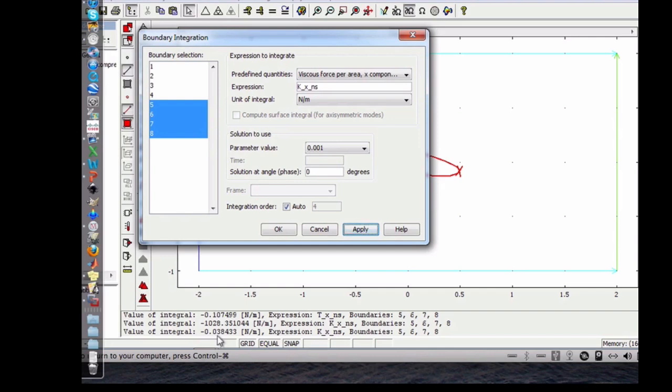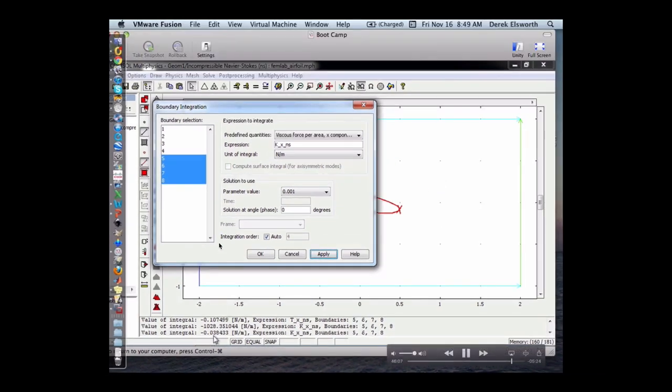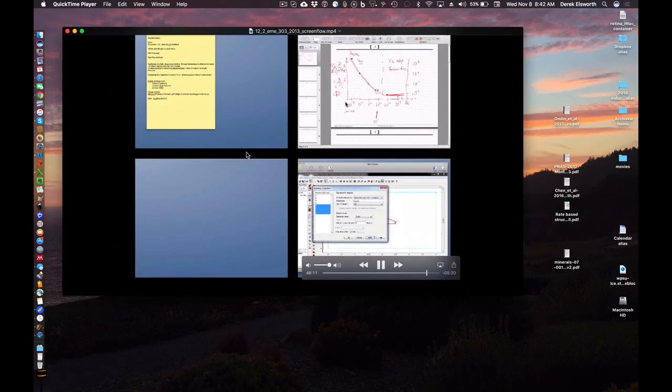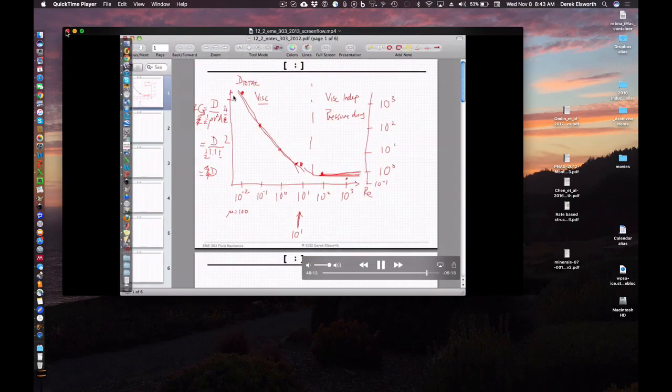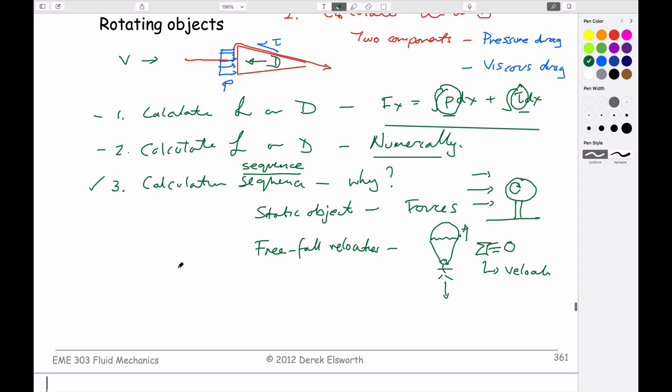So the viscous drag, instead of being 70%, is now only 30% of the total drag. As we go up to progressively higher and higher Reynolds numbers, the influence of the fluid pressure drag will completely dominate behavior, and therefore we get exactly this behavior.